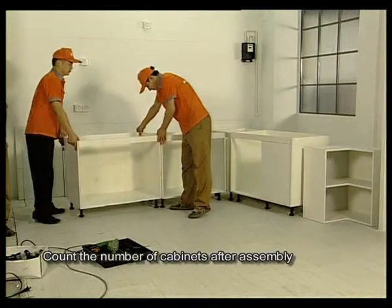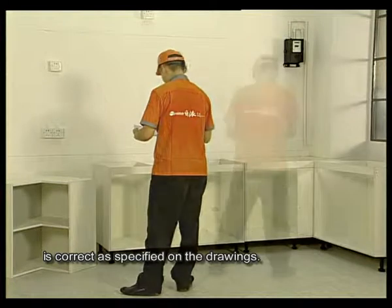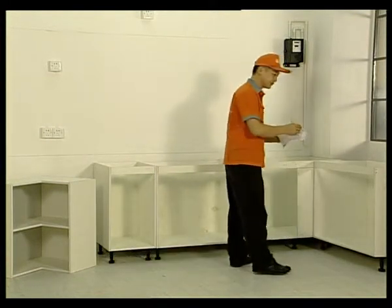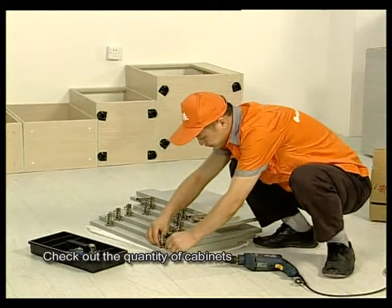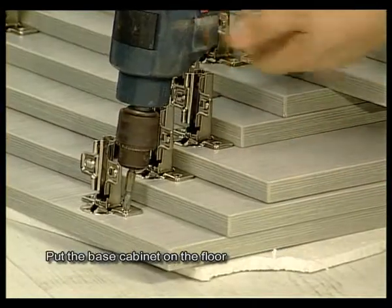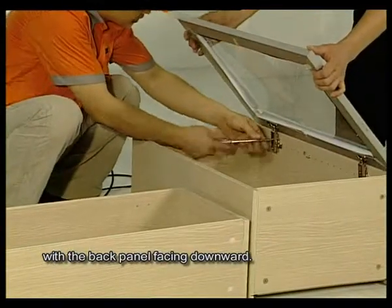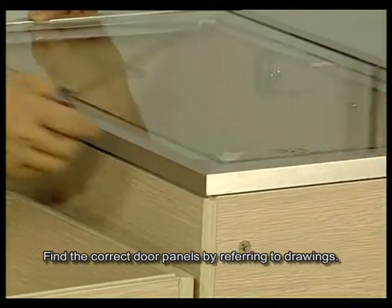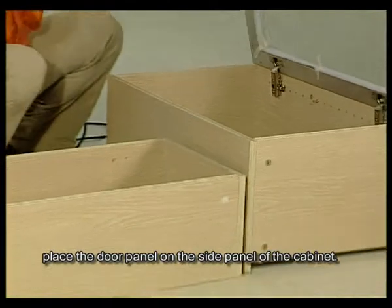Count the number of cabinets after assembly to ensure the number of cabinets is correct as specified on the drawings. Check out the quantity of cabinets and then install the hinges on the door panels. Put the base cabinet on the floor with the back panel facing downwards. Find the correct door panels by referring to drawings. In the end, place the door panel on the side panel of the cabinet.